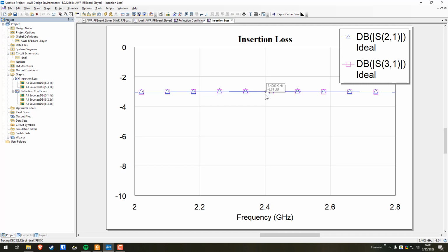It's a two-way power divider, shall we say, right? So it basically goes two ways. So if you take something divided by 2, then that's half on each side because it's an equal split. So we have -3 dB. Even if we go all the way to the left edge of the band, we've got -3.047. That's very nice. And all the way at the top end of the band, 2.8, we're looking at -3.047. So again, this is awesome.